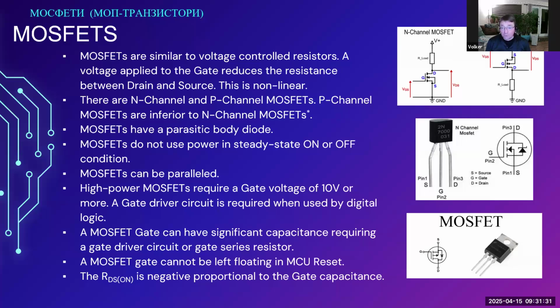The high voltage MOSFET gate drivers are designed, also with a bootstrap capacitor, to use two N-channel MOSFETs, not a P-channel and an N-channel, which would be the natural idea: a P-channel for the upper side of a bridge and an N-channel for the lower side.